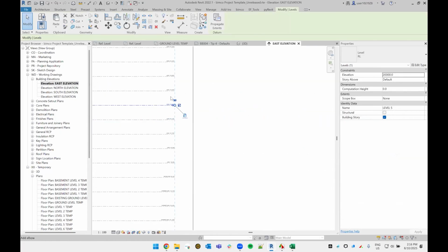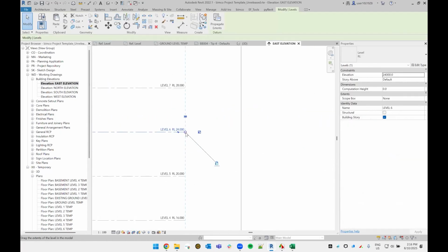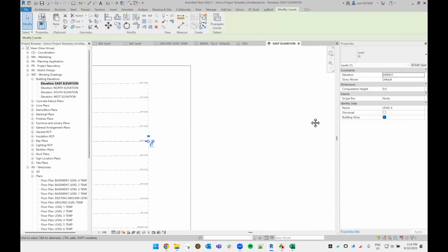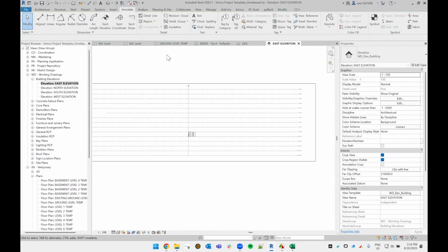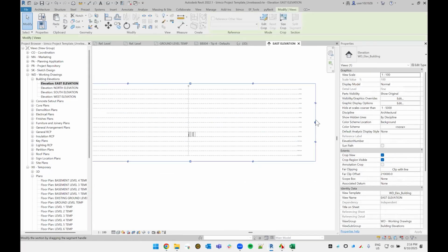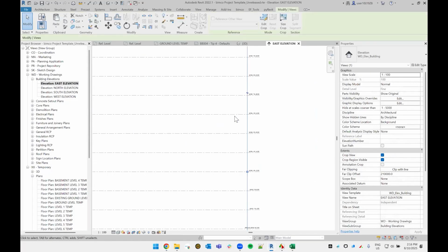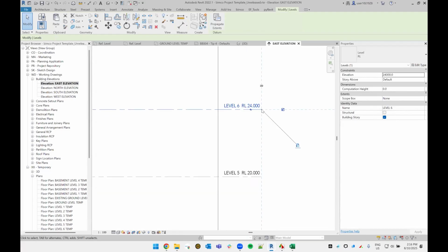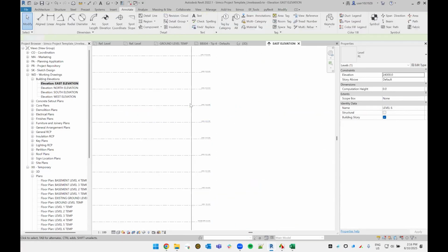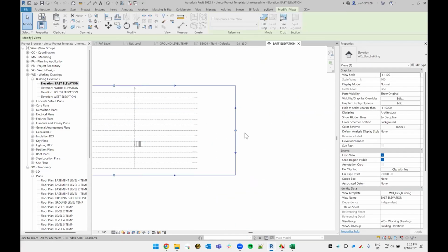So it's incorrect. You always want to click the level and drag it in an elevation. We've really done it very carefully to a very particular dimension. So avoid the use of cropping. In other words, don't go cropping some of these things. You'll turn these into 2D extents like that, and then you'll be changing them and wonder why they're not actually shifting in 3D.